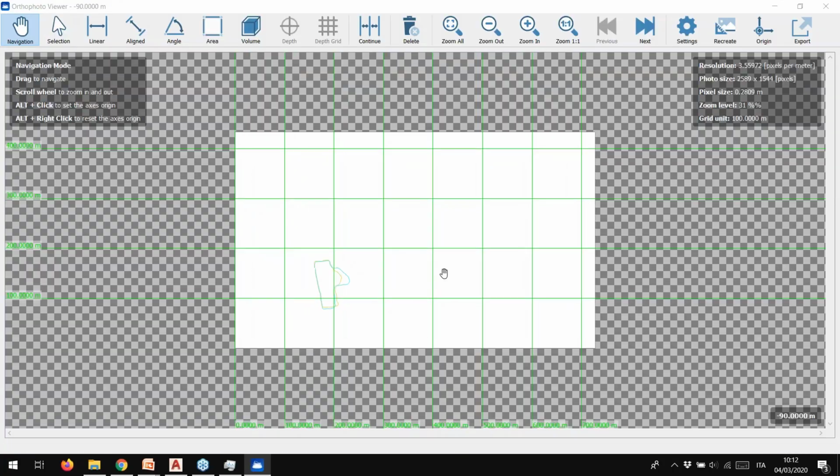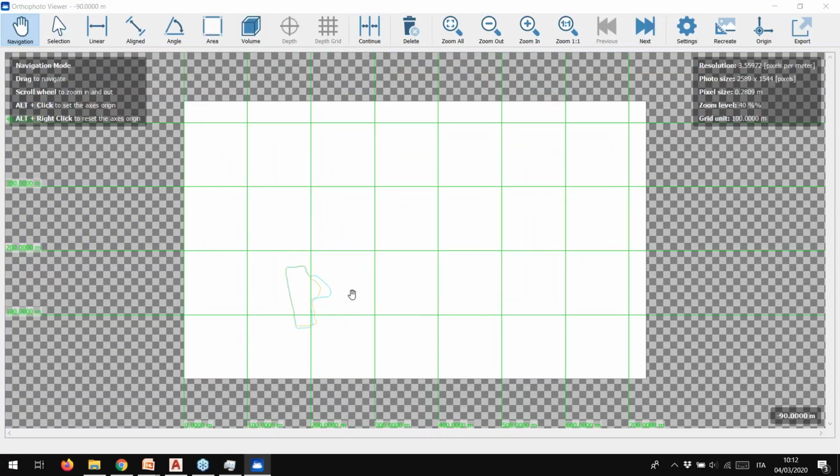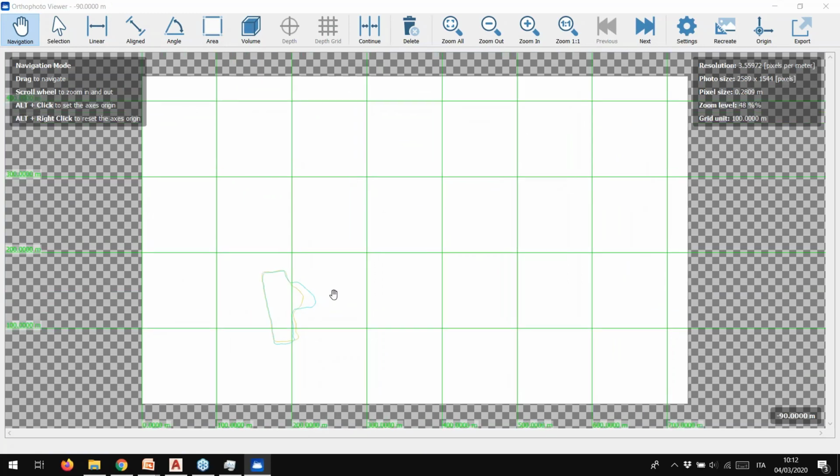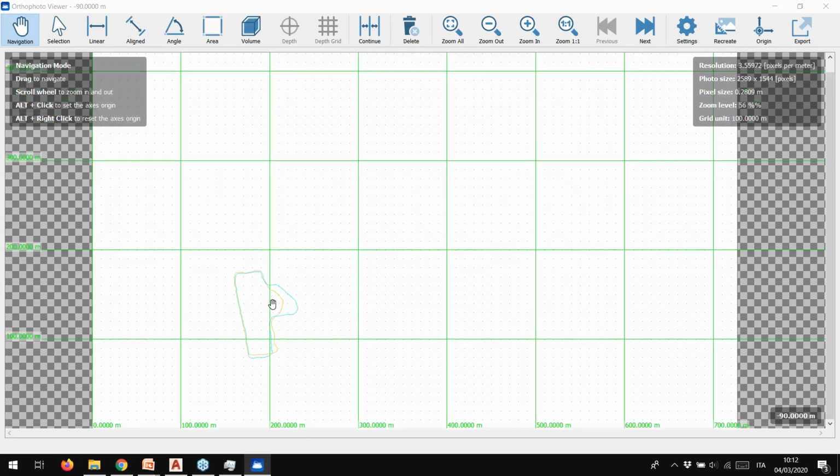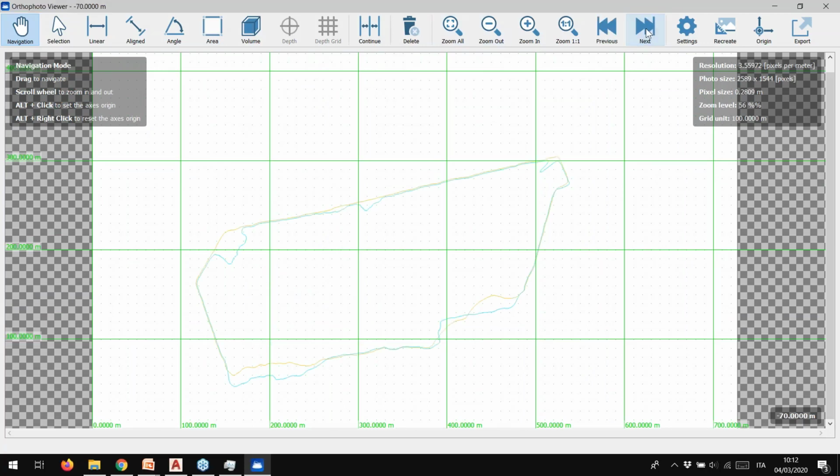Remind that you can run the contours extraction using more models, so if you want to define and estimate the differences between two models, like check excavation or blasting, for example, in the section viewer you can visualize the polylines results extracted by the two models, as we are displaying here.